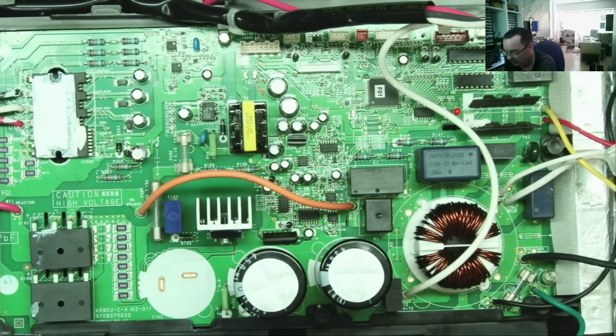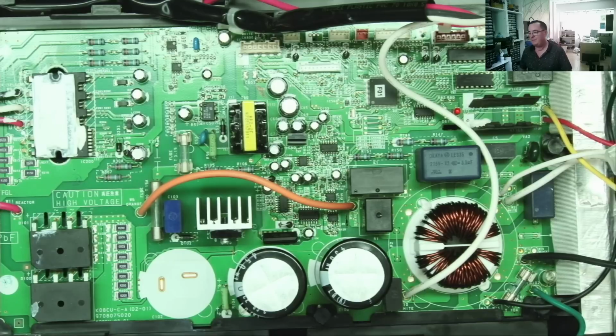And the third one is, if we take the information online that this is an EEPROM fault, then can I program that EEPROM in my EEPROM programmer? And if I can, can I get the firmware for this? Yeah. And where would I find it? So I'll go away and have a think for a while. Yeah, that's about as far as I can get in this session.